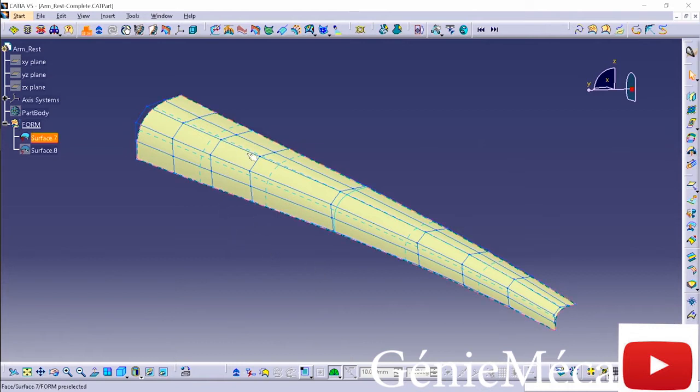These control vertices or hulls or control points, depending upon what system you're using, as they're called or referenced, are again controlling the shape of that surface. For a surface that requires a lot of shape, you're going to require more of these control vertices as well as these internal patches. The more shape that something has, the more control it requires, the higher the math. So you're going to need a lot more of these control points.